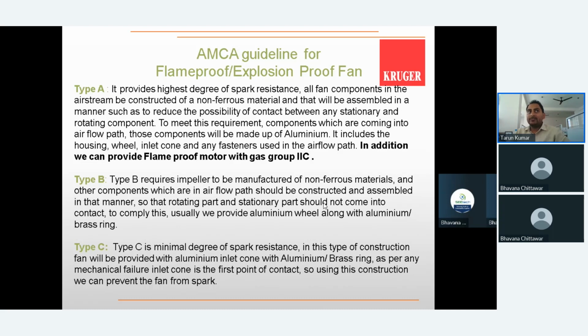In multiple cases, we are seeing that at the same time the BOQ calls for the spark resistance type, it will also ask for the smoke exhaust. So I just want to clear it out. A smoke fan cannot be used for spark ventilation, and a spark resistant fan cannot be used for smoke ventilation, because both the motor features are different.